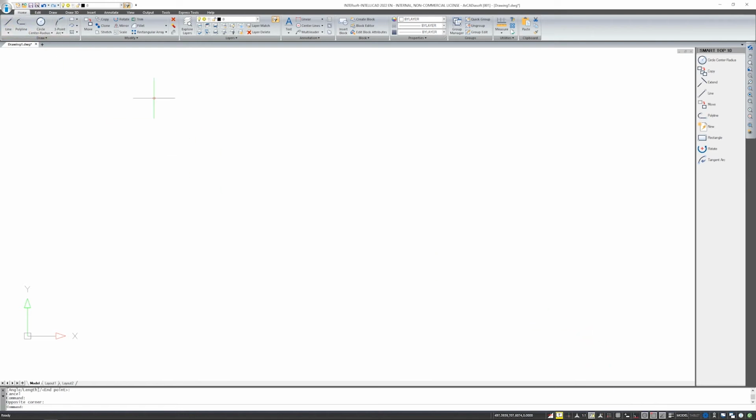So here at the bottom, in the status bar, I'll turn dynamic input off. And I'll introduce the first line in such a way so it will start from point 0, 0. So I type 0, 0 on the keyboard. The comma is the separator between x and y. The period is the value separator. So for example, 12, and then half of it will be 12.5. Remember that the period on the numeric pad is actually a comma, so keep this in mind when entering data.